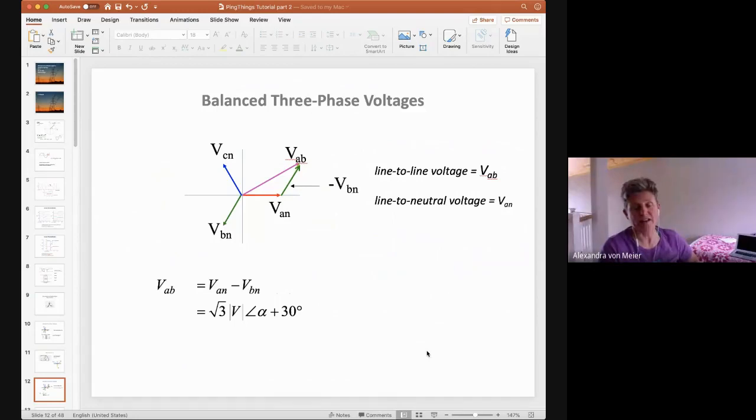So this motivates the fact that we're going to see a 30-degree phase shift between them. And there's also that factor of a square root of 3 that I talked about last time without deriving it. But from the phasor diagram, you can do a little trigonometry and work that right out. So the upshot is, if you're connecting something between a pair of phases A and B, you get a bigger voltage by a factor of √3 than if you connect something between one phase and neutral. And there's also a phase shift, which you can draw pictures to remind yourself if it's plus or minus.